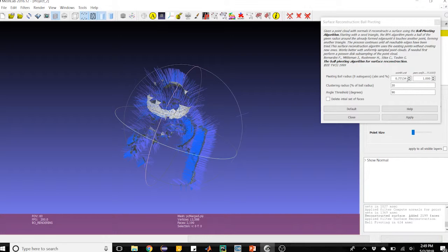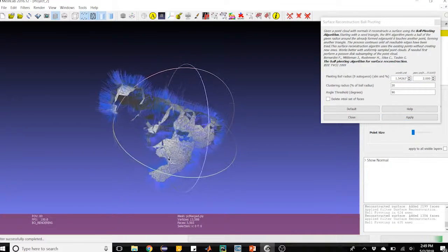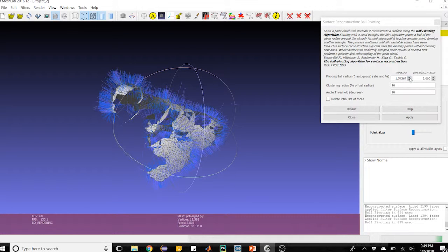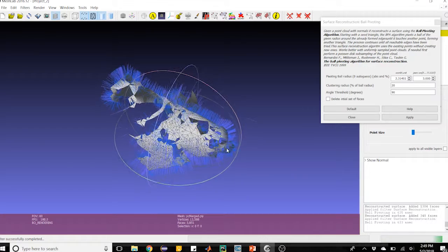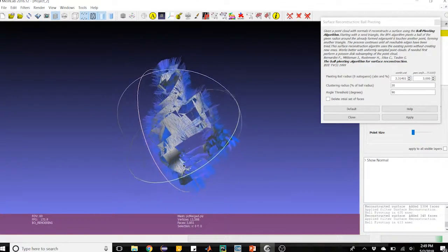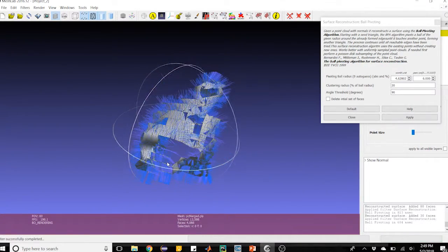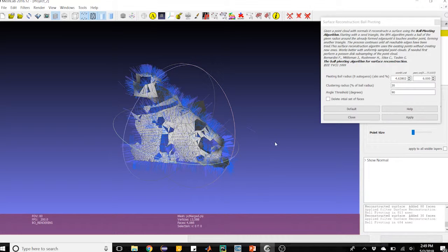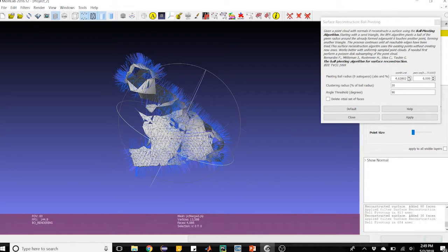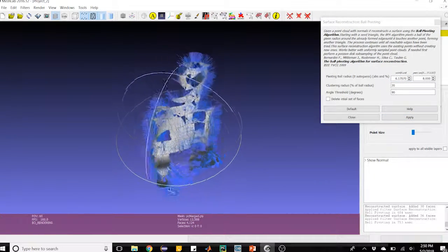Some things that could fix this are a denser point cloud so that the mesh algorithm has an easier time connecting the points. Additionally, another map from the underside of the cannon would help fill in data from the bottom. I couldn't get my Lidar instrument low enough to take data from this angle, so there's no point cloud data at that point, and therefore it made it really hard for the mesh algorithm to recreate the smooth surface on the underside of the cannon.